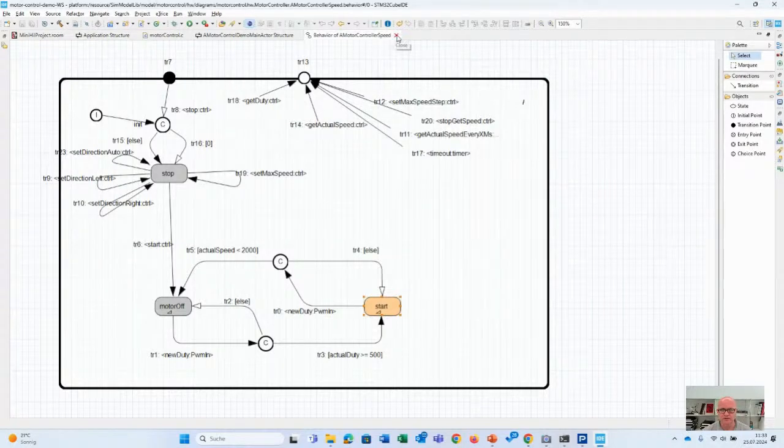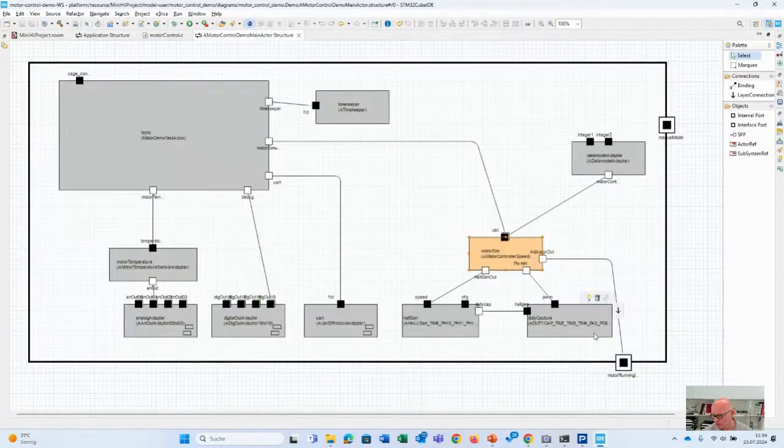If you already have a simulation model, a Simulink model, for example, you can use the Simulink plant simulation you're using also to generate C code integrated instead of the state machine. You have a Simulink block in there. That works pretty good because you do not want to redo the motor simulation. So you can reuse existing models if they can generate C code, for example.